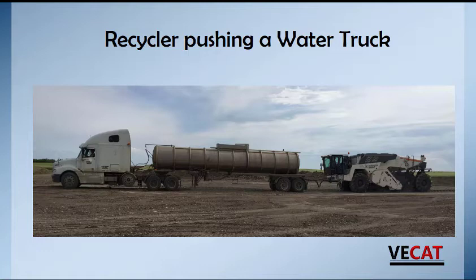A good note about this is when you are connected to a truck and using the push bars and pushing a water truck like this, be very mindful of dropping the water tank and disconnecting. Your hose itself is about 10 foot long, will hold 2 or 3 gallons of water. And if you just drop it right in the middle of the recycled mat or pulverized mat, then you could potentially flood that area, and we've lost all the accuracy that we have. So when disconnecting, try to throw the hose off to the side of the road in the ditch and let it drain there.